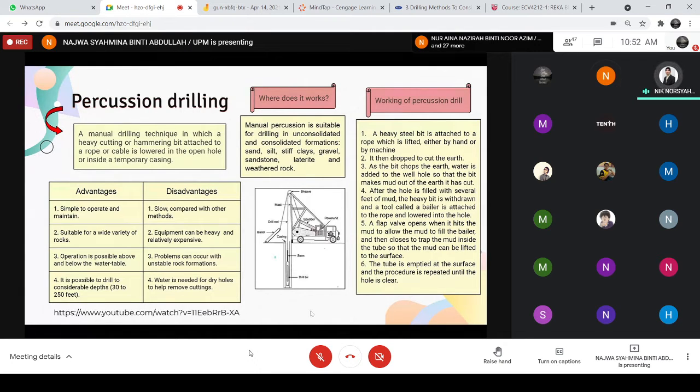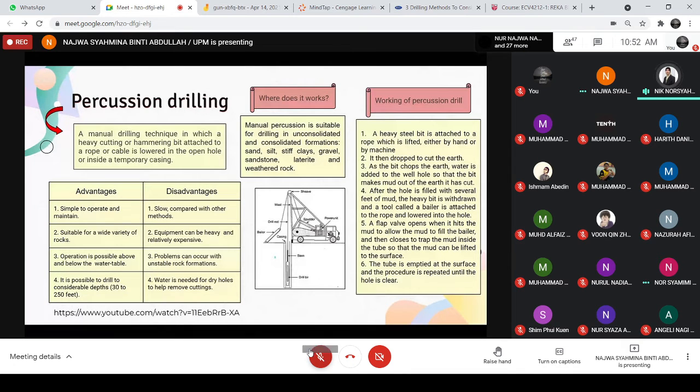So this is the method that we discussed: drilling holes to prepare the boreholes, to find samples and to get data. It's not yet data, though. After taking samples, you carry out tests in the labs, and only then do you get raw data to analyze.